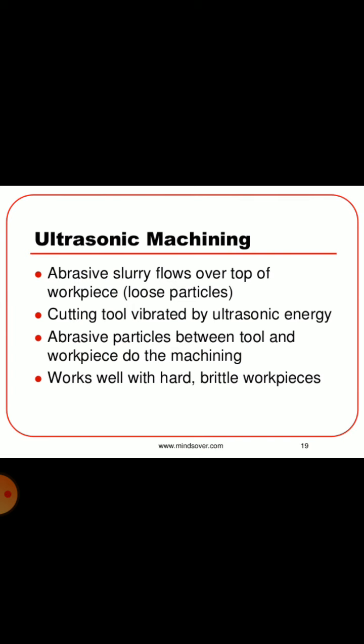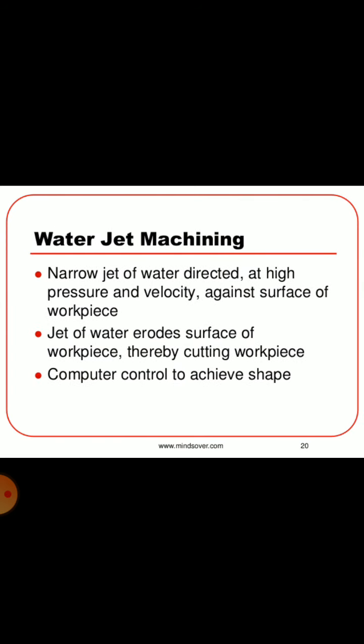Another process in unconventional machining is ultrasonic machining, in which abrasive slurry flows over top of workpiece, that is loose particles. Cutting tool is vibrated by ultrasonic energy. Abrasive particles between tool and workpiece do the machining. Works well with hard brittle workpieces.